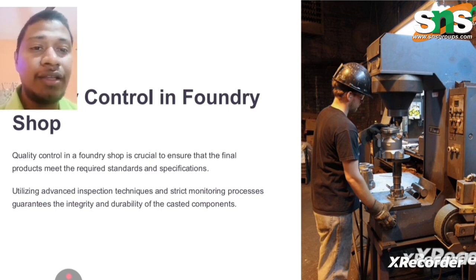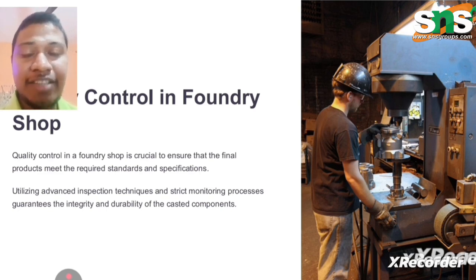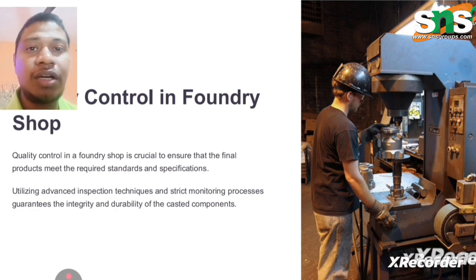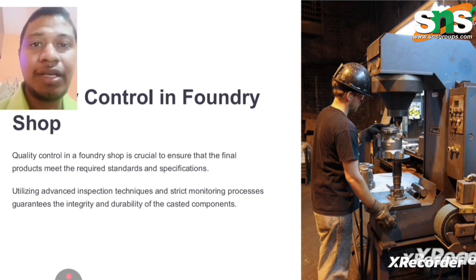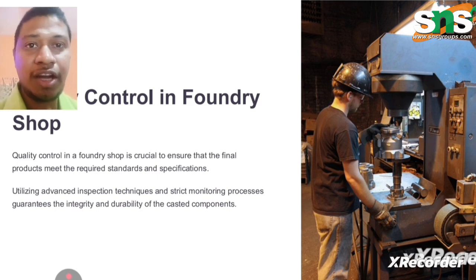It may be monitored with the help of UV ray detection, in which we can see pinholes or air bubbles formed due to pouring of molten metal into the casting. That can be removed using machining. If it cannot be removed using machining or any other operations, it will be scrapped.